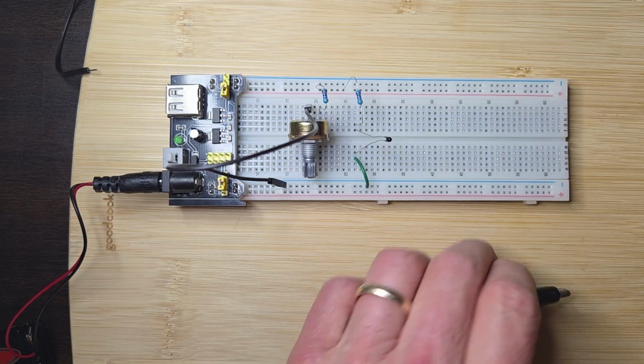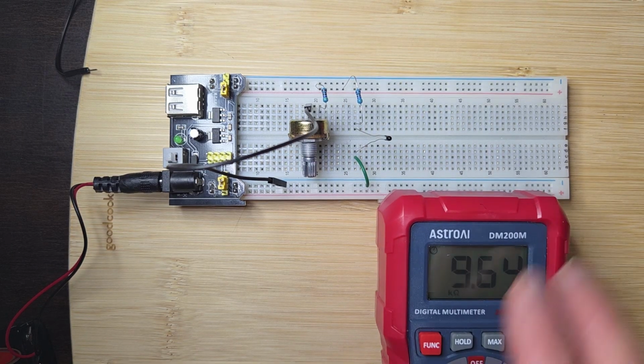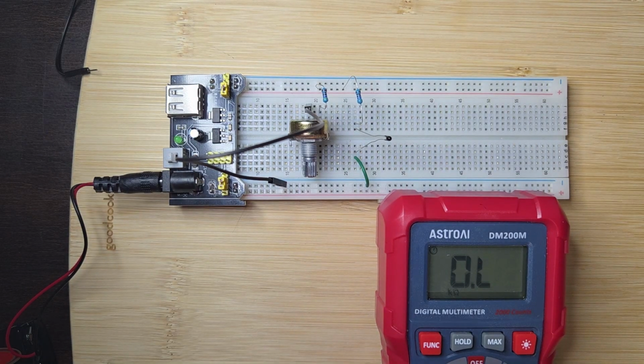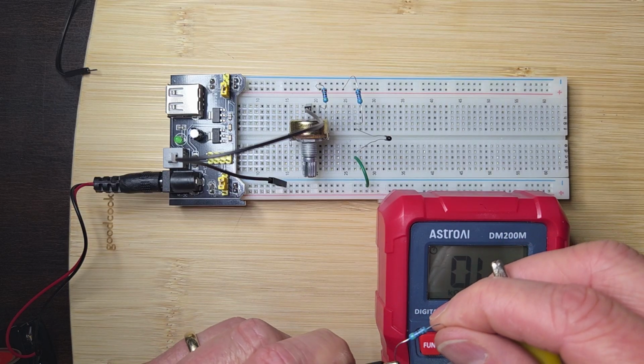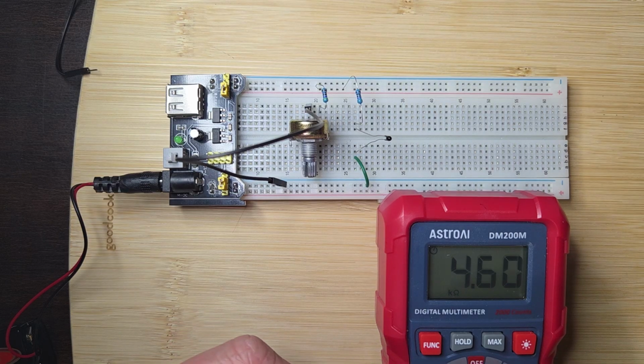And to do that, I'm going to see if I can find a resistor. I'm just using what's at hand. Now that's 10K. That's a little too much. One thing about these, you don't want to use a lot of resistance. I wouldn't want to use like a 100K ohm resistor because it's harder to balance the bridge when you've got so much resistance in there. So you want to pick something. I probably wouldn't go over 10K ohms because then you've got more chances for error.